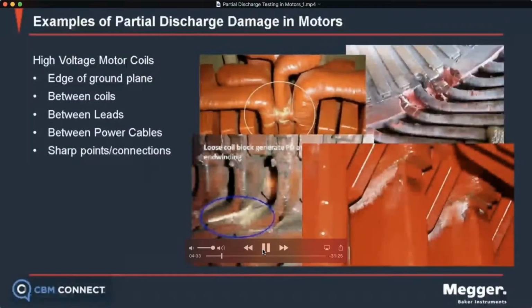Okay. In the motors, right? So high voltage motors, as I mentioned, 6,000 volt motors typically and above. You can see these types of evidences. Again, that powdery deterioration of the external surfaces of the insulation is the most common visual representation of corona activity that can happen.